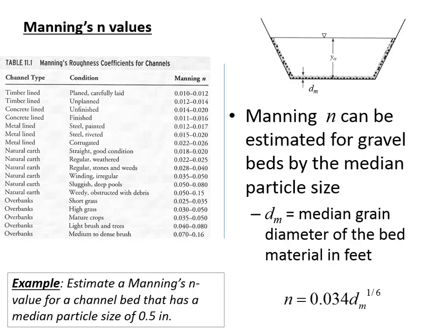And if you've got big stone cobbles, maybe riprap of broken up concrete, you're going to have a larger n value, because here, the larger the grain diameter, the bigger the n value, but it's to the 1/6 power is what they estimated. The n value increases to the 1/6 power of the grain size.